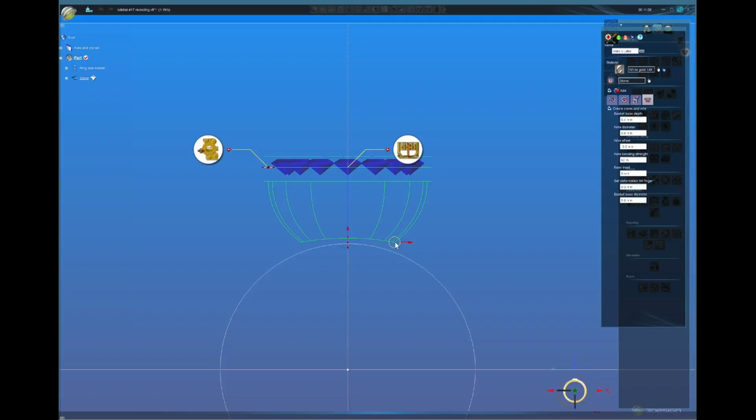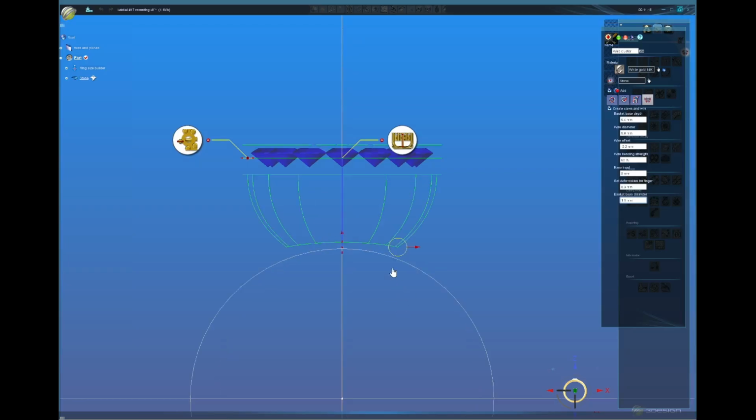We're gonna fix this now. This is the basket base diameter, and I'm going to do 1.1. I don't want to leave it too thick, but not too thin either, because you might notice that some rings have this wire so thin, and considering that polishing and everything makes it so thin that it's almost breakable. I want to leave it a little stronger to better support the cluster. So let's leave it as 1.1.